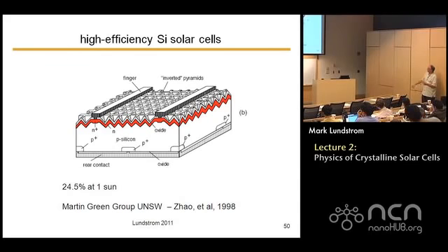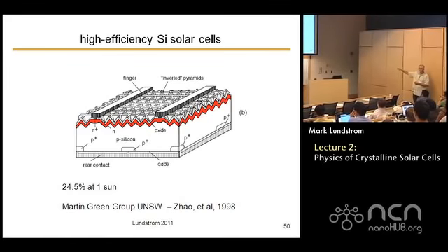Now, if I design the thickness of that oxide just right, it can promote the reflection of photons back in, so it can benefit the optical design. So people are just enormously careful about how they design these cells. They run simulations and calculations like the ones I've talked about. They find out where most of the recombination is occurring. They try to figure out a structure that will suppress that recombination. Then you look at it again, and now the dominant recombination might be somewhere else in the cell. Then you work on that and see if you can lower that.